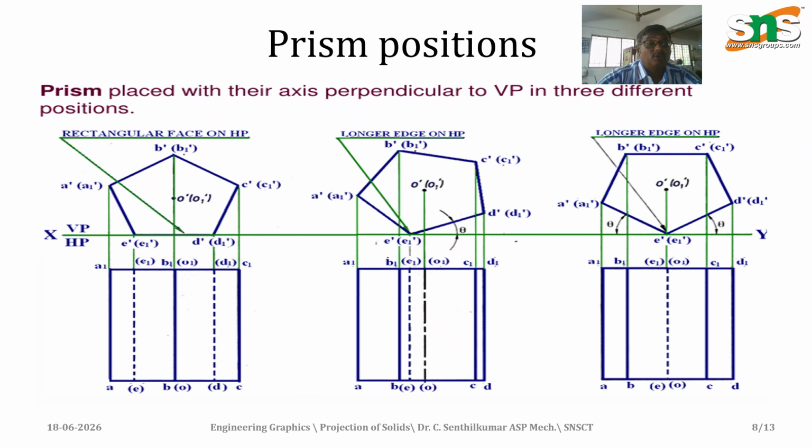After drawing the front view, we draw the top view. In the top view, a rectangle is drawn with the size indicated in the problem. This is the axis line. This is the dotted line. When you see from the top, this part is not seen, though it is indicated by the dotted line. This point is also not seen from the top. It is indicated in the top view as a dotted line, named without dashes because it is a top view.